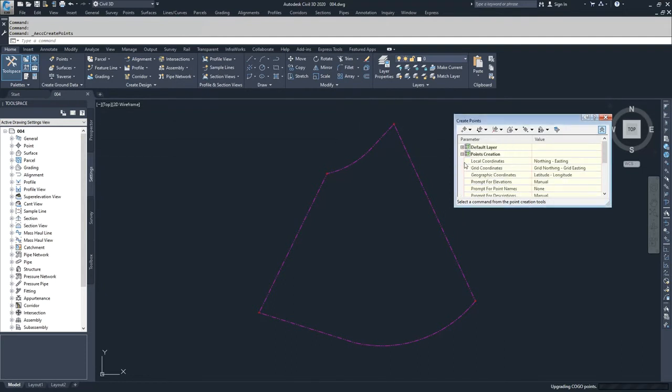So moving on from here, we have our default style. If you had set your disable description keys to true, then when you create a point, it would accept its point style and point label style. In here, these are grayed out, and that's because we have this set to false. If we had this set to true, you'll notice these become ungrayed and you can choose them.